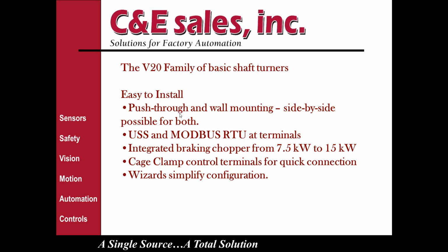From a communication standpoint, the V20s are limited to just USS and Modbus RTU, and those are brought to terminals on the front of the drive, so you can easily wire to those for networking. But again, those are limited to just those two protocols. Both are RS-485 serial communications links. In some cases, you may require additional communications modules on your PLC or other devices to communicate with the V20s.